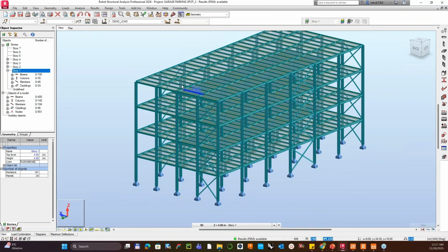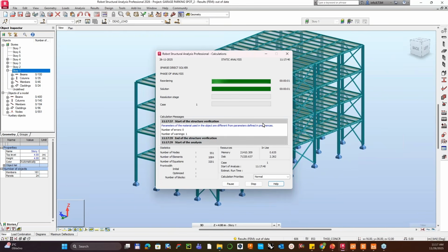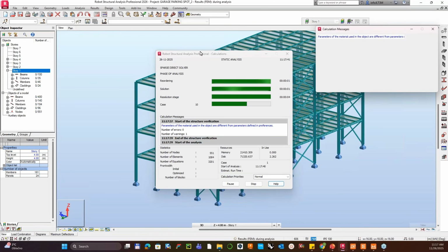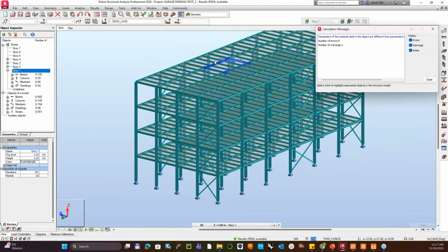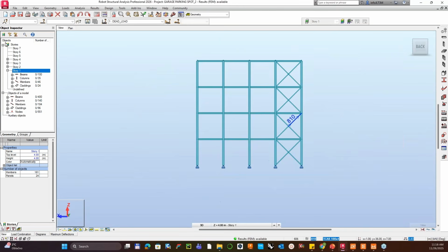If you have a structure like this, at first you need to calculate the internal forces. So run the linear analysis to get the internal forces. If you have it, you will just double check, like a sanity check, if everything is fine. So you need to have this plugin installed. This plugin exists in add-ins for this tool in the IDEA StatiCa. So if I do that, I can just export the whole structure. But this is not my goal, because I would like to work with just part of the structure.